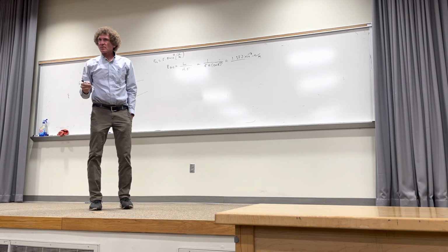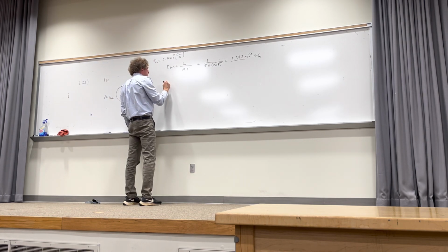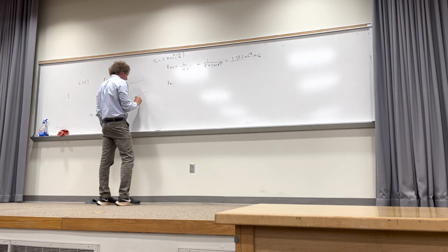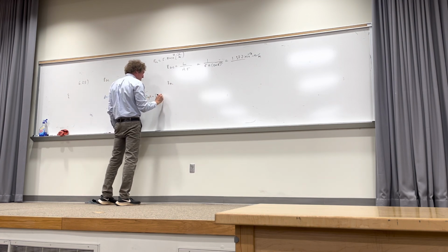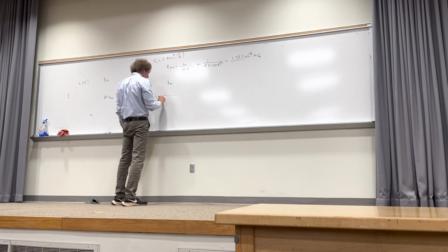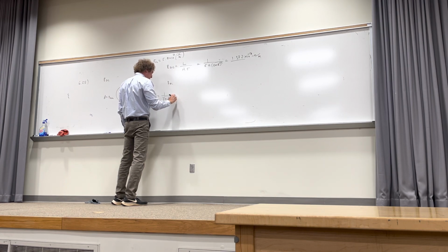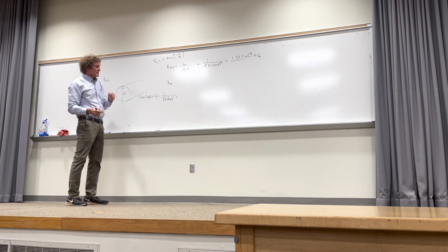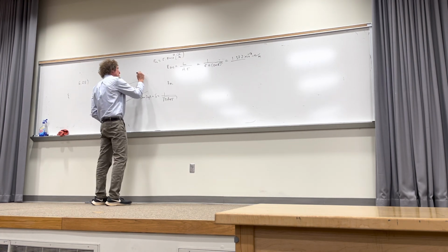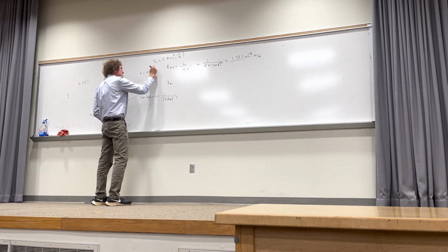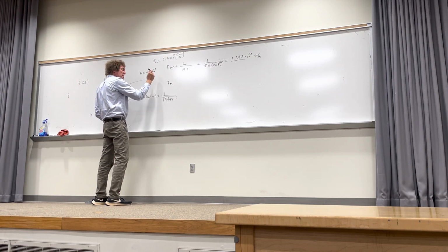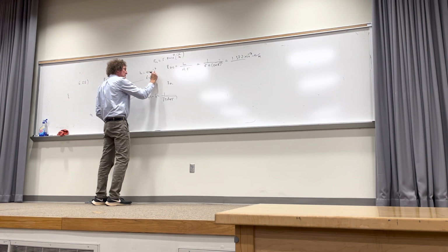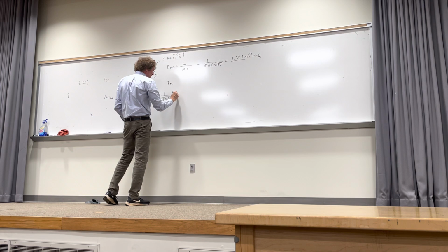Okay, sounds reasonable. Now, when we take a look at the AC resistance, the first thing we have to do is calculate the skin depth. And skin depth is something you're going to have to know for Friday and for the final. It's 1 over the square root of pi f mu sigma. Here, sigma is copper, so it's 5.8 times 10 to the 7th. Mu will just be mu naught, which is 4 pi times 10 to the minus 7th. The frequency you said is it 2 gigahertz? 1 gigahertz. All right, so it's 10 to the 9th hertz. And can you give me that skin depth? I want the skin depth first.